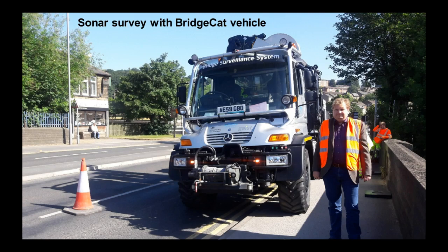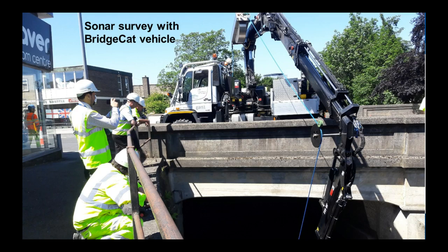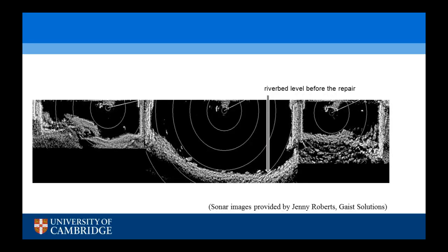The first thing we did was carry out a sonar scan with the Bridge Cat vehicle, which is owned by Cumbria Council. This vehicle has an extendable arm with a sonar head at the top. The sonar head can be put into the water, and we can take images. These are three sonar images overlaid with each other to get the bed profile.